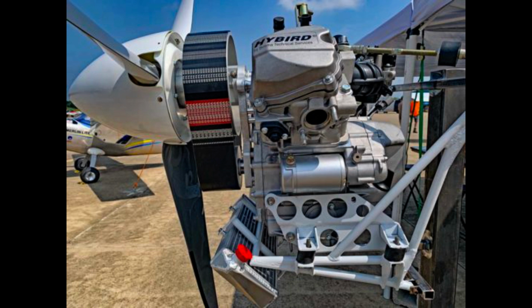If an engine is revved too quickly during takeoff before warming up, a lot of heat is generated on top of the piston. This quickly expands the piston, which can then seize in the cylinder. A piston seizure will stop the engine abruptly. The second area of concern is lower in the engine around the crankshaft. This is an area where parts may get too loose with heat, rather than seizing up.